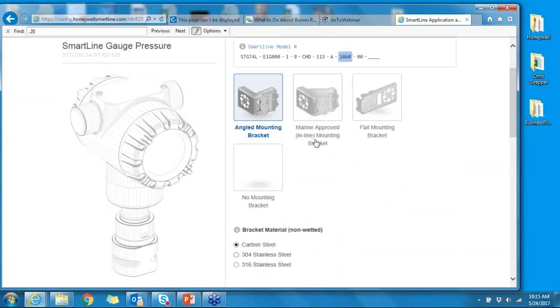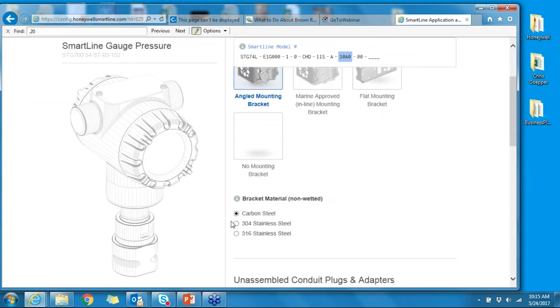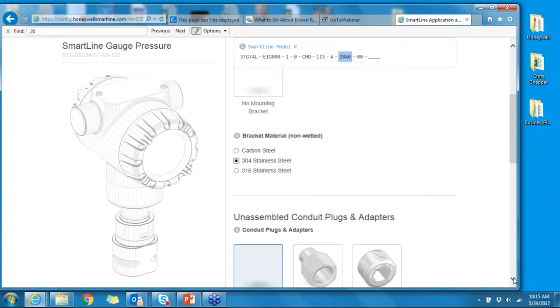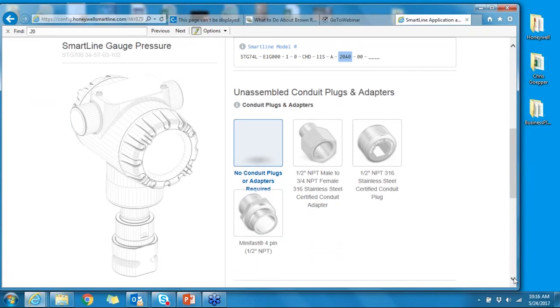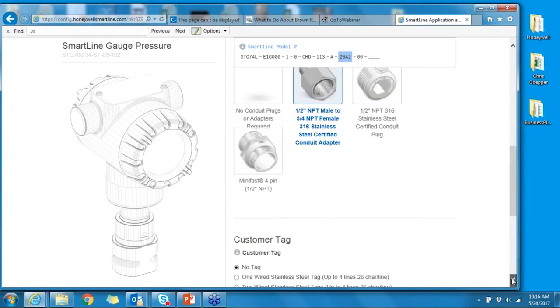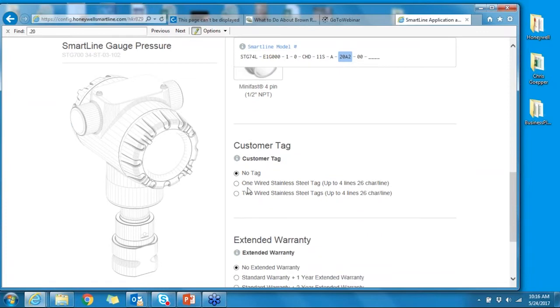You'll see next our communication output is pre-selected at HART. I'm not going to change that. My fail mode, I'll leave it high, and also leave my write protection as is. I'm going to want a standard display as opposed to a blind display, which is what is selected. There we go. And I'm not going to need any buttons for this one. I'll leave the 3-button module off of it. And we'll keep this in English. And I will click Next.